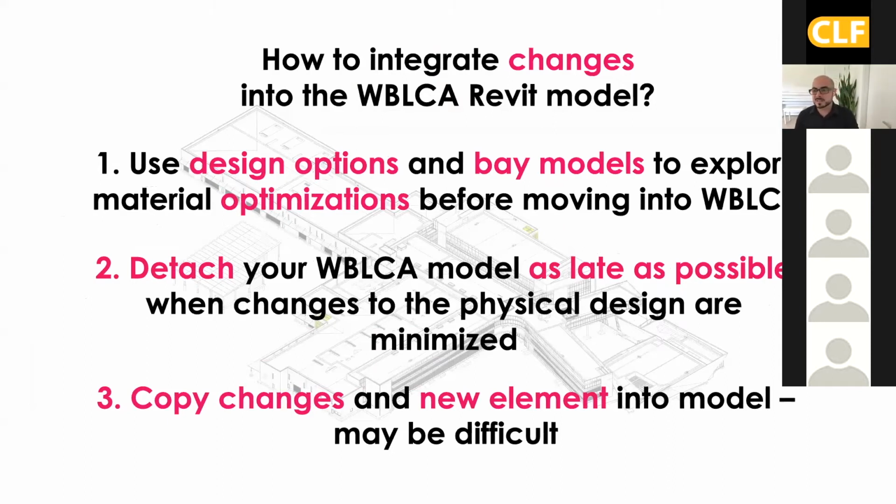Now, this is a common question that we often get in LCA presentations: how to integrate changes into a whole building LCA Revit model. And the answer is that it's just really hard to integrate changes into a whole building LCA. So again, the best workflow would be to start small with assembly models and bay models.